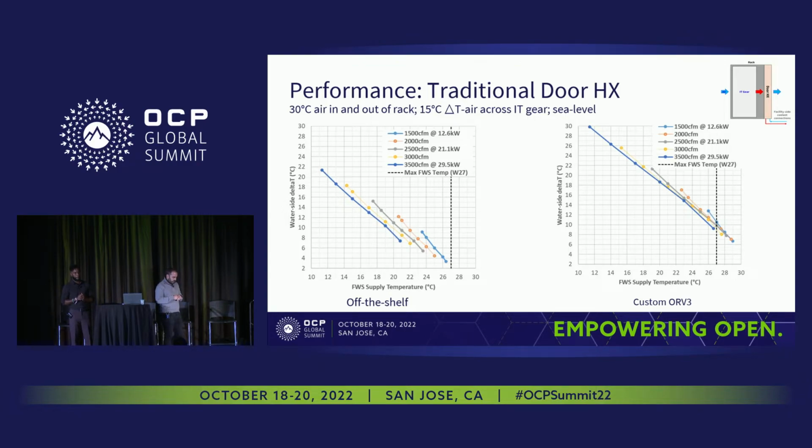So, a very important point here, which we spoke about, is the water supply temperature. If we are able to increase the temperature to 27 degrees, compared with the OTS, we will be more efficient globally. And it is possible to do that while also maintaining the temperature difference in the water side of the reactor at 8-10 degrees.